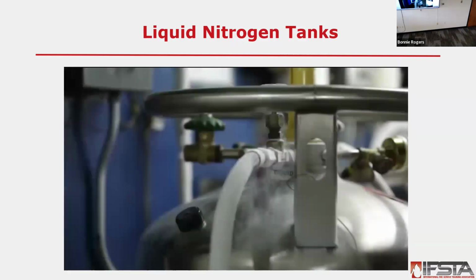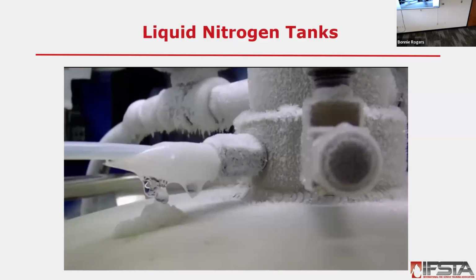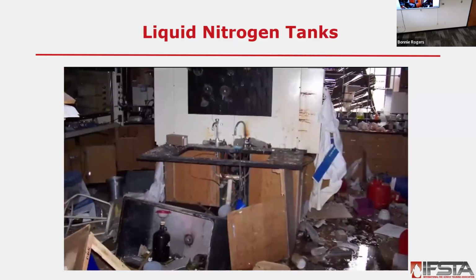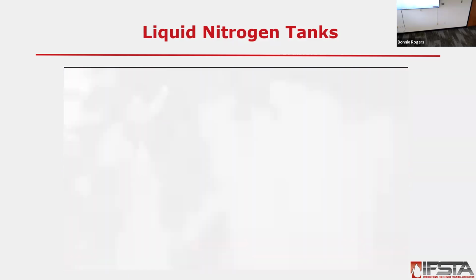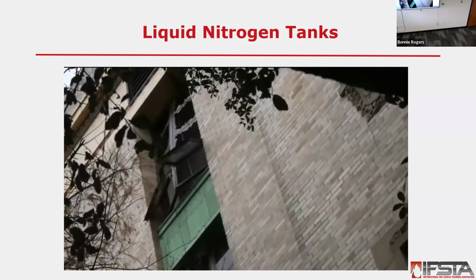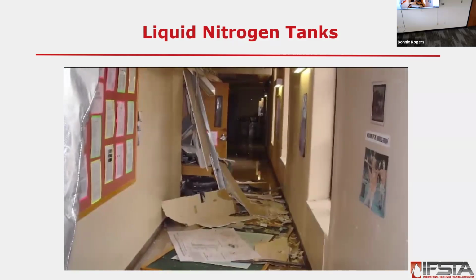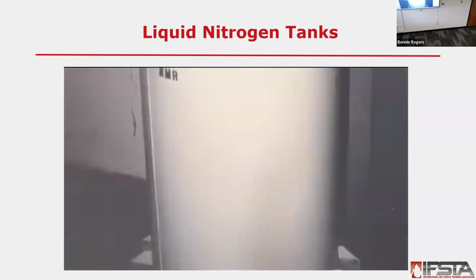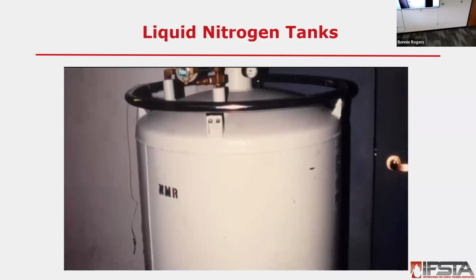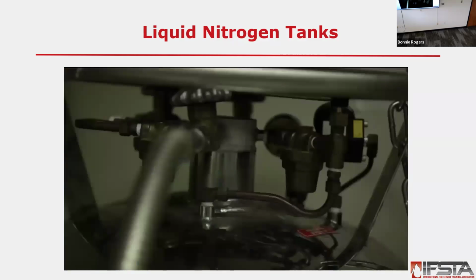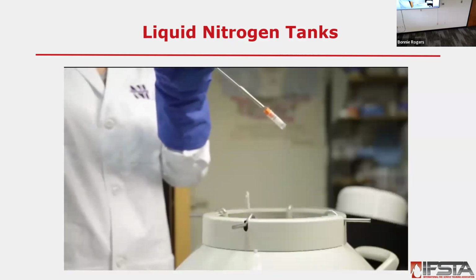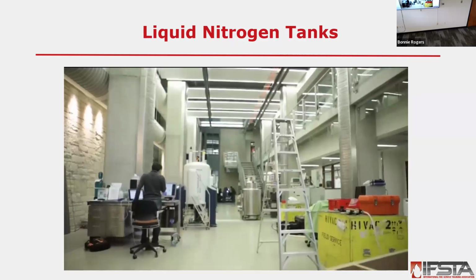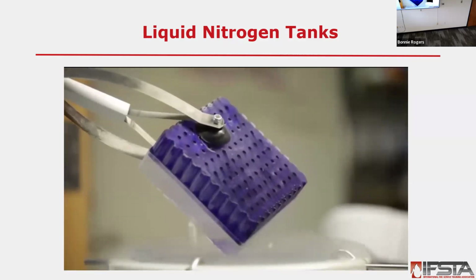Expansion. Liquid nitrogen can expand up to 700 times when changing from liquid to gas. Rapid changes in temperature can result in rapid or explosive conversion to gas. Rupture incidents have occurred in university laboratories after users had inadvertently altered or obstructed safety relief devices, or tanks became dented and compromised. Pipes, vessels, NMR tubes, and cryotubes with trapped liquid can violently rupture, causing injury and exposure.